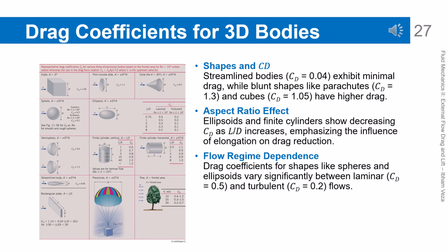In addition, the CD value also strongly depends on whether the flow is laminar or turbulent. For a sphere, for example, CD in turbulent flow is much smaller than in laminar flow. This shows that both shape and flow condition are equally important.